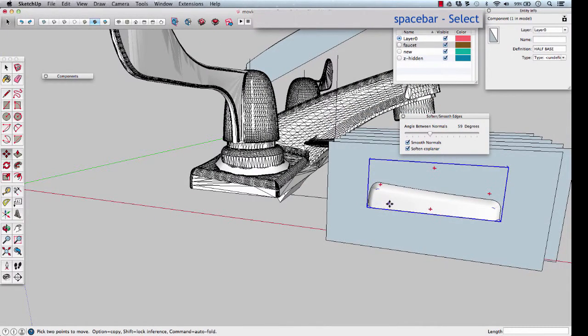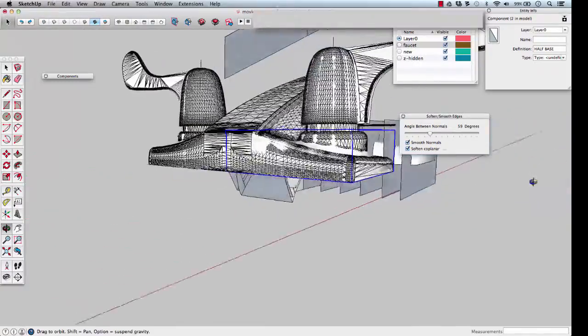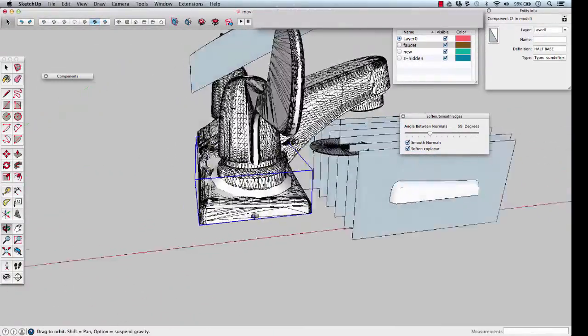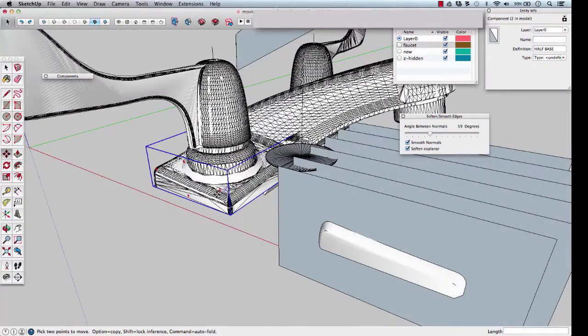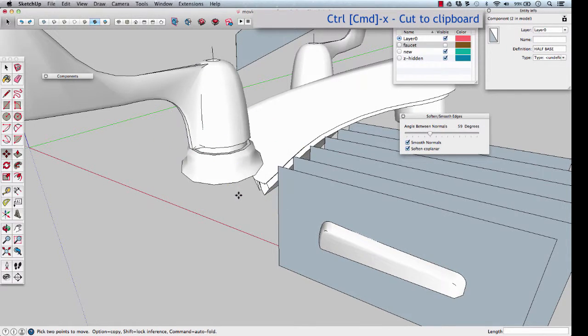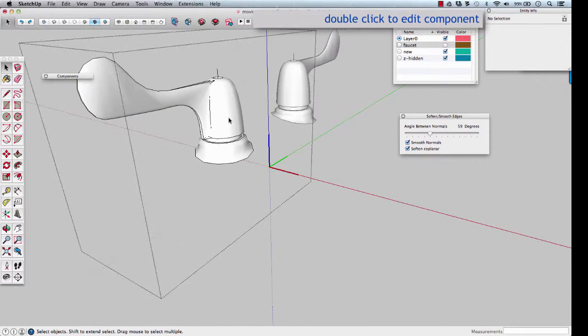Click and select it, move it, or copy it back in the red, a distance of 10. Now we can play with that one back there, but it'll be reflected out front here. We want this piece to go inside of our other half group. So it's selected, cut it away, Control X, Command X, spacebar, and double click into our half.